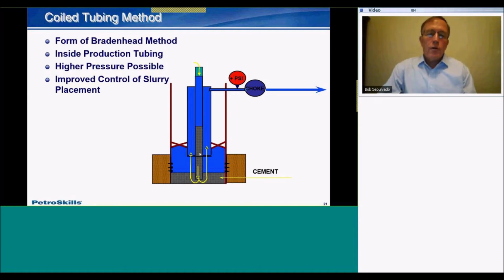To pump a cement slurry in that type of environment and make it conducive to flow and move, there may be materials added to it to make it more rheologically fit for that type of environment. I'm talking about adding materials like dispersing materials, which is fine if that's what's needed to be able to pump it in there. But the thing to be aware of with dispersing materials is, as they thin the slurry, we still want the slurry to be stable. Slurry stability is a key at any point, but especially in an application like this, because we don't want to be pumping at a very low rate and have separation of solids and water create problems.